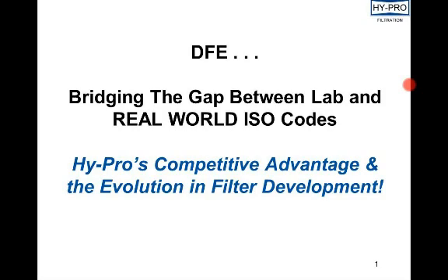Okay, thanks, and thanks to everyone for participating in this webinar. We're going to be talking about DFE, which stands for Dynamic Filtration Efficiency. It's a new way of testing filter elements used in hydraulic and lube systems, and a new way of developing medias that are more stable and that better retain the contaminant that they've previously captured. This test method was pioneered by Hypro in the early to mid-90s, and we've continued to build on it and continue expanding the testing capabilities.